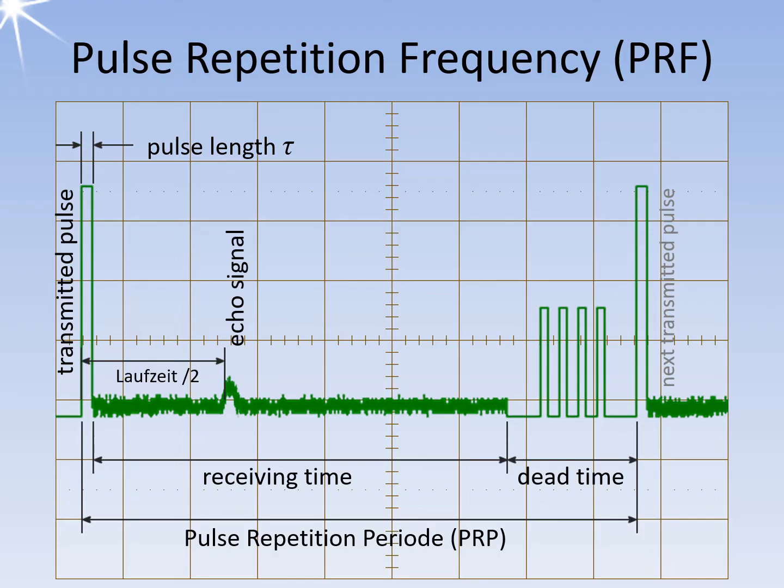This recovery time occurs when the duplexer switches off the receiver because the transmitting power is too high. However, if the transmitting power is low, the receiver may be in working order during the transmitting pulse. In this case, the reception time includes the transmission time.